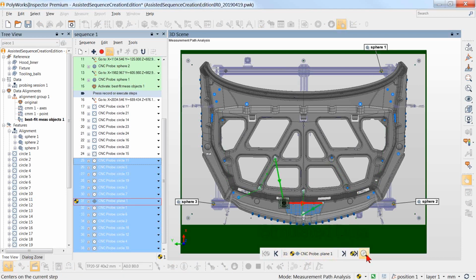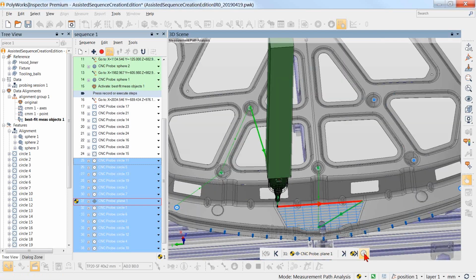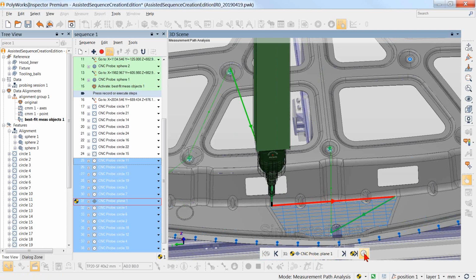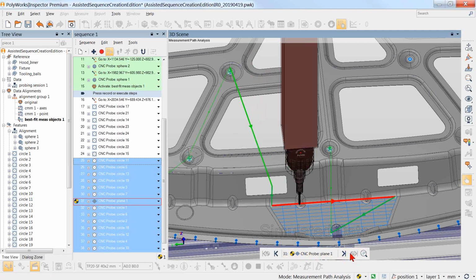And one of the nice things about this is you don't have to zoom into that. You can actually have that command inside where this will go through and show you, okay, here's us zooming into the path. Now, I want to step through this path to show me where the collision is going to occur. So in this case, the procedures that were done to measure this, or the properties of the plane, did not take into account that little piece of a stiffener that was there in the forming of this.